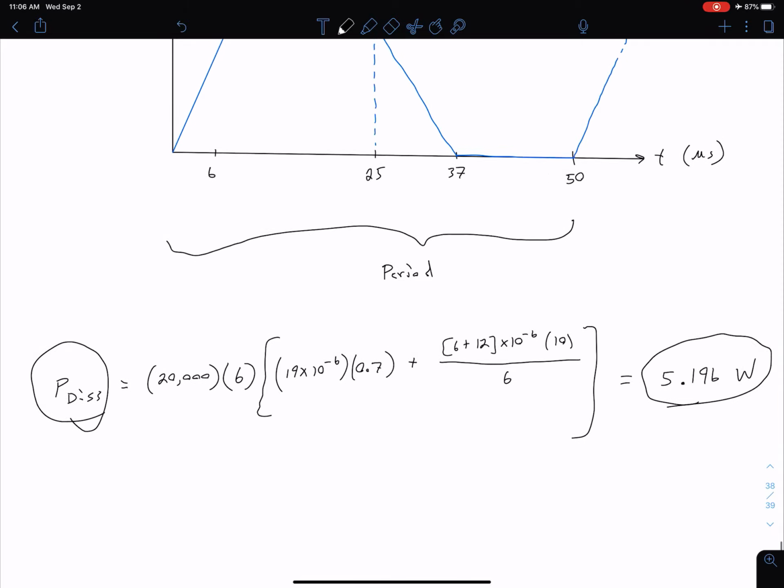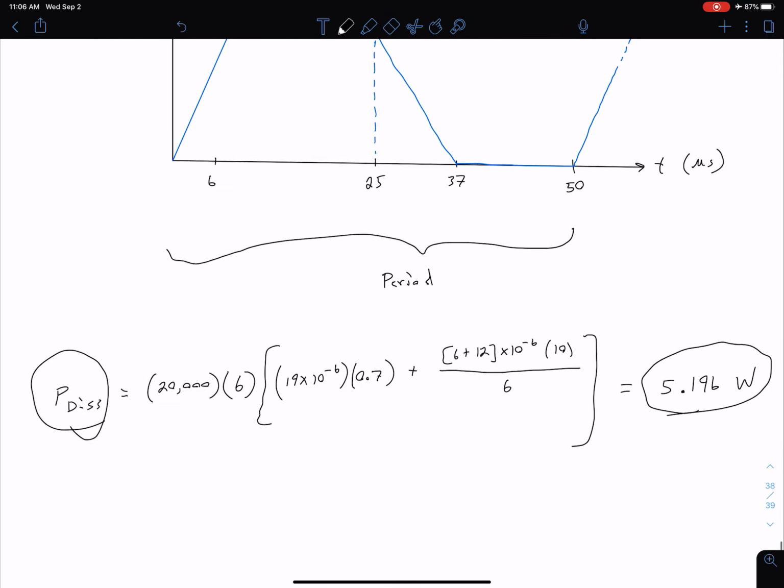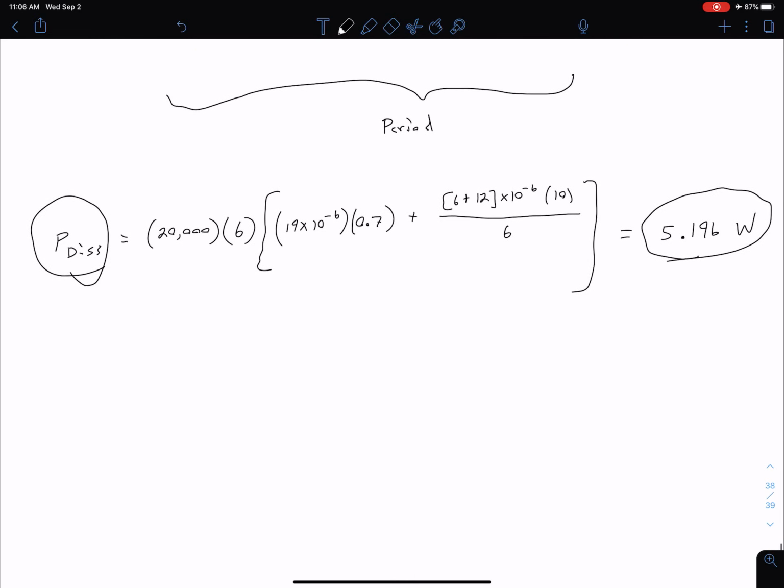We can compare that then to our approximate 15 watts of power dissipation for our linear voltage regulation. So we have a much improved power consumption, and we haven't even tried to optimize this design. So improved power consumption with a non-optimized design. And what do I mean when I say non-optimized design?